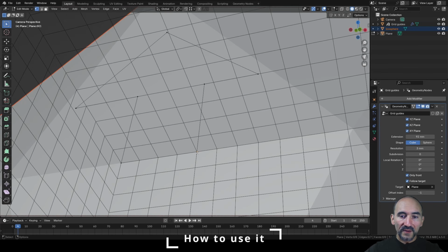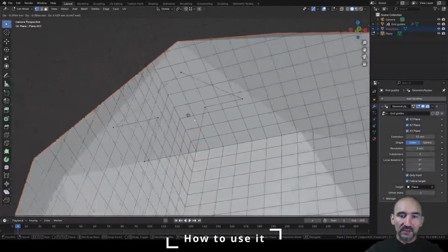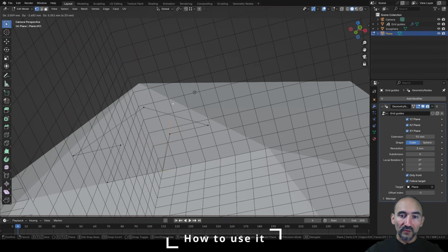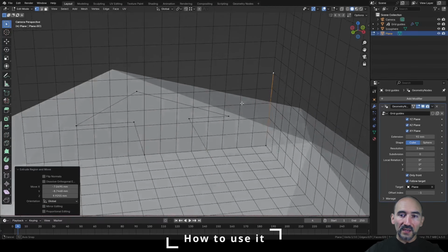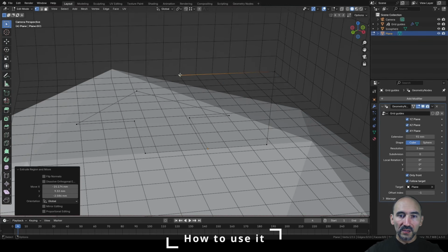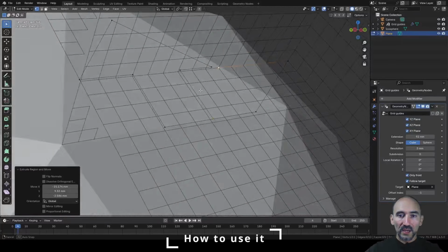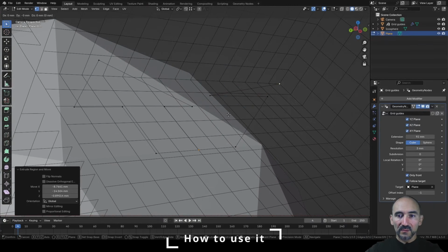So now if I take this last index and extrude, and I want to go perpendicular to this point, I can do it, and I can press G and move using the control, and then use the extrusion and go up, okay, perpendicular, as you can see here. And then I can go again in this direction, pressing extrude another time and go here. And maybe I want to place the new vertex diagonally like this, and maybe another time in this plane, so parallel to the original face I started to work on.